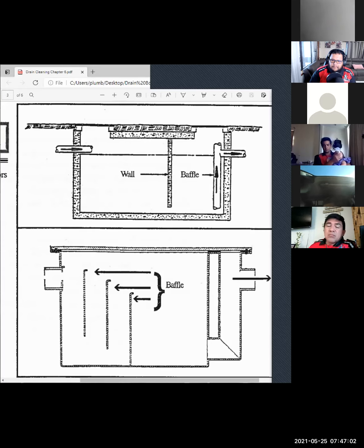Mantles are supposed to be there because that's how a grease trap works. The thicker the mantle, the more grease they've collected that has not gone into the wastewater system. So just because you see a thick layer in it doesn't mean it's full. Once again, if it's 5 feet deep, 6 feet deep, and you poke something through there, you'll be able to tell the thickness of that mantle.